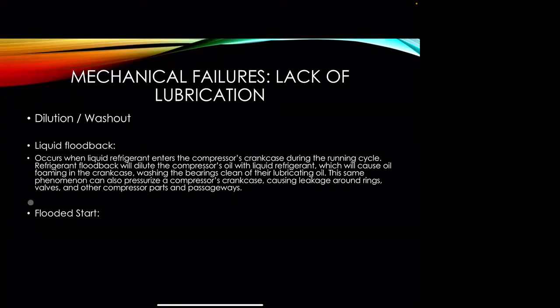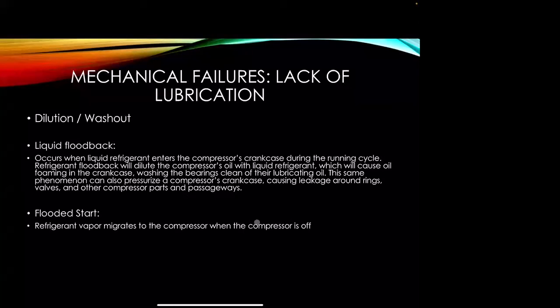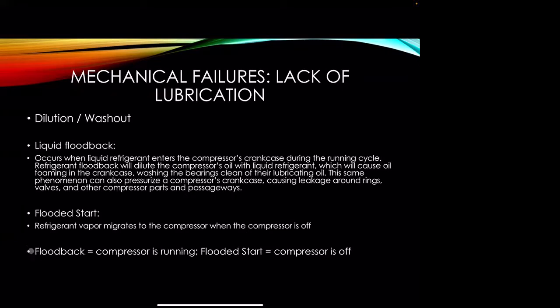The other one is flooded start. Flooded start is refrigerant vapor that migrates to the compressor when the compressor is off. Liquid floodback during the running cycle, flooded start when the compressor's off. So again, put it down here one more time. Floodback, compressors running. Flooded start, compressors off. So just think, when it starts, it was off. That's when we had our flooded start. Floodback is when it's running.